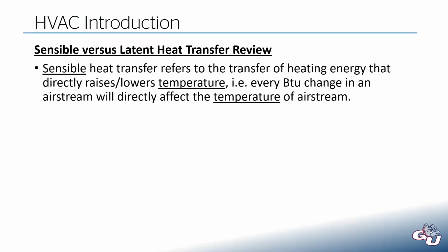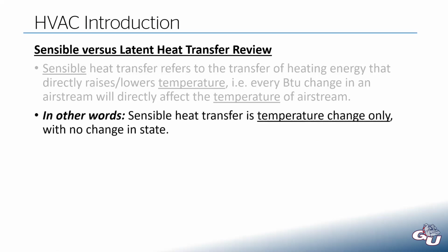Sensible heat refers to any transfer of heat energy that has a direct correlation to raising or lowering the temperature. So every BTU change in an airstream, whether it's heating or cooling, only affects the temperature of that airstream. In other words, sensible heat transfer is all about that temperature change and nothing else, with no change in state, which you might be scratching your head about because that might seem like a duh kind of statement.